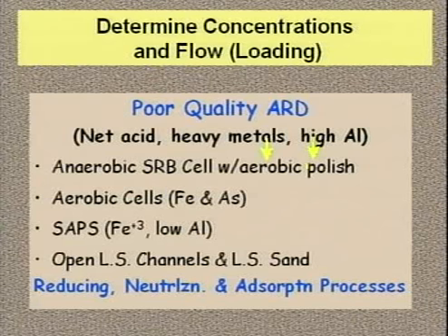That's this one. You precipitate the metals as sulfide and polish the SRB cell effluent with an aerobic cell. In some cases, you might want to consider limestone-dominated systems, but they might not be enough to provide the results that you need.